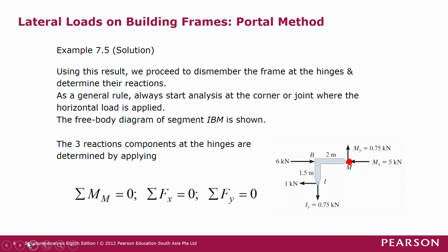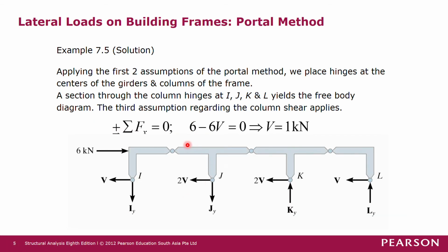Next, we move on to this particular part of the structure. Okay, so take note that this hinge is common to this free body diagram and to this free body diagram as well. So when you take the internal forces at these hinges, okay, they must be complementary to each other. So this is in accordance with Newton's third law.